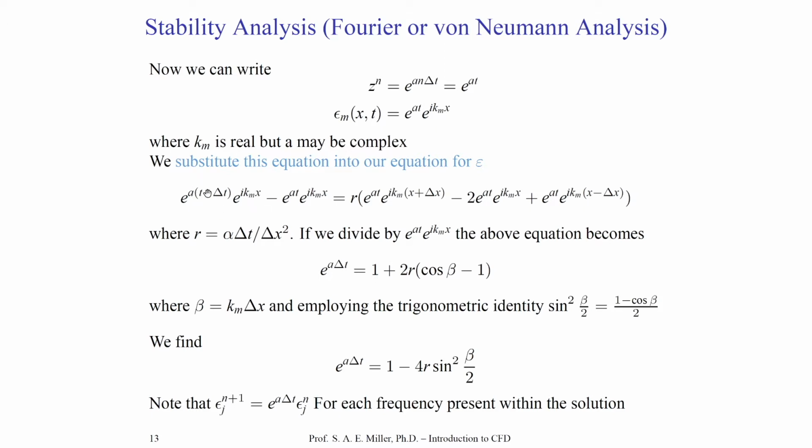In fact, when you read out this whole equation, it looks very much like the original discretization. Why? Because here's the time advancement term. Here's the term at the current time level, and the left-hand side would be that original partial derivative discretization with respect to time. The right-hand side, of course, is the spatial discretization. Here's the original term, alpha, which is the heat conductivity coefficient, times delta t over delta x squared.